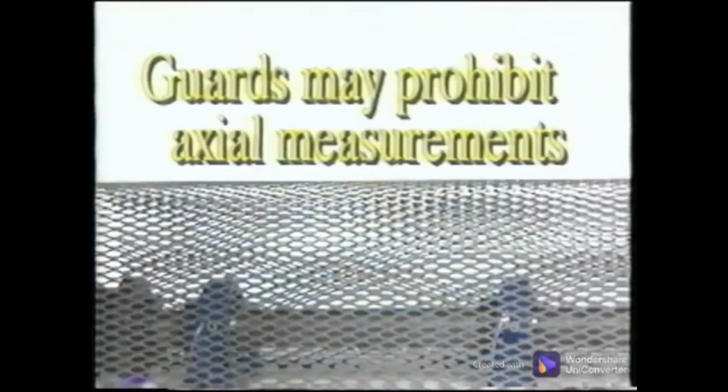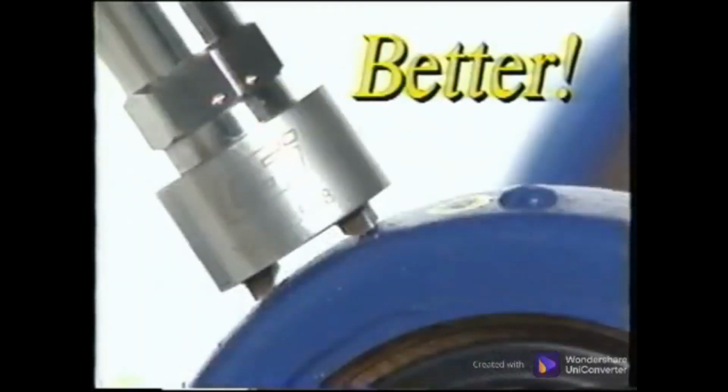thrust. Pillow block bearings on shafts like this may be inaccessible due to guards, covers, or simply be out of safe reach. If the guard is mesh, the long stinger may be used to reach through it for the radial measurements. Although the stinger or long probe does not provide the best data, it is still far better than no data. However, it is important to collect an axial measurement on each pillow block bearing, and the guards or covers often prevent that. A better way to measure the covered pillow block bearings is to install a hatch door so that a magnet mount sensor can be used.